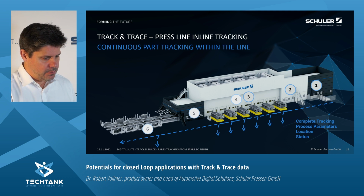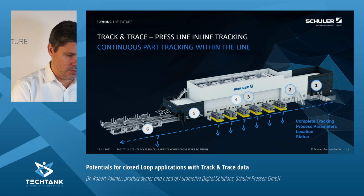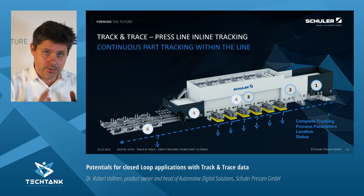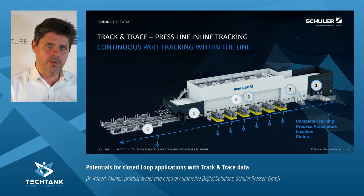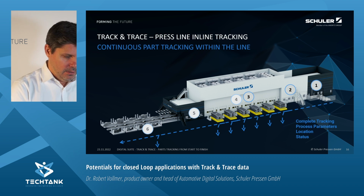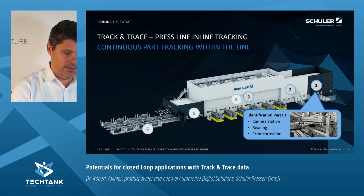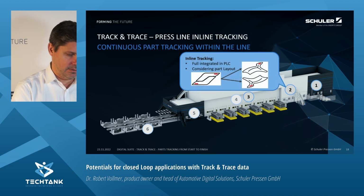So now switching to the press line, we are focusing also that we do continuous part tracking, not only on the front of line or the first press stage, we do it really through until the end of line area. We start typically with the identification of the part ID. That means we have a camera station, we read the codes and have an error correction at this stage.